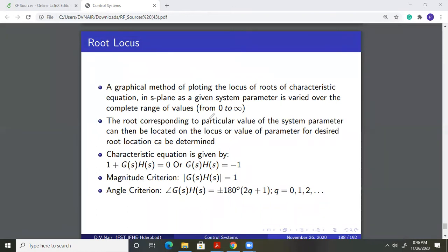like in the case which we just saw before, our root locus was something like this. It originated at 0 and minus a, and at minus a by 2 it was breaking away from the real axis. The two branches started on the real axis at 0 and minus a, met each other at minus a by 2, and later they left the real axis, and the roots later on became complex.